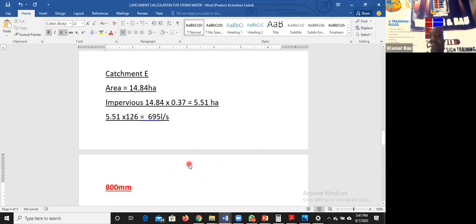That's why in pipe design, sometimes you don't have to do the whole sizing. Once you've done for 10 pipes, like we do in reinforcement, those of you that are civil engineers, if I have a beam that is 4 meters and I have a beam that is 5 meters, if I do a beam of 5 meters and I get my reinforcement size, if I see a beam of 4 meters, I can confidently say a beam of 4 meters can carry the reinforcement of 5 meters. But I cannot say a beam of 5 meters will carry the reinforcement of a beam of 7 meters, because that is not in the direction of safety.